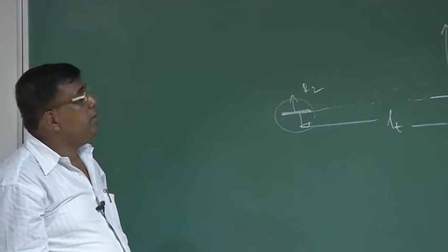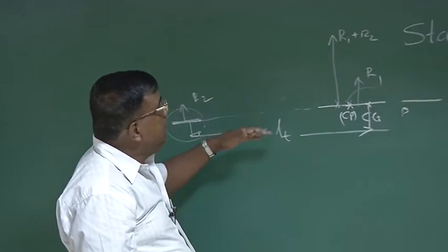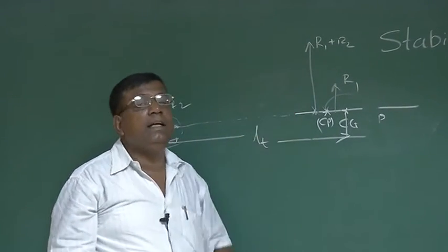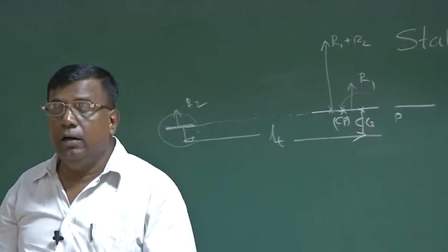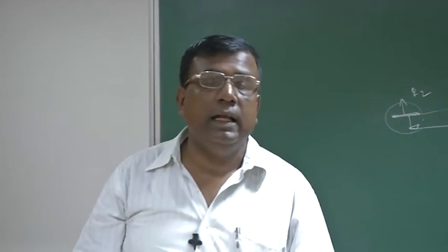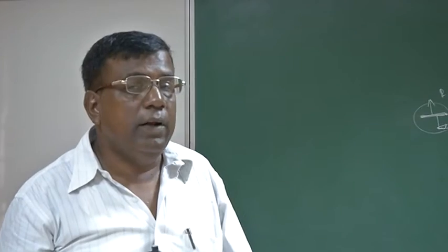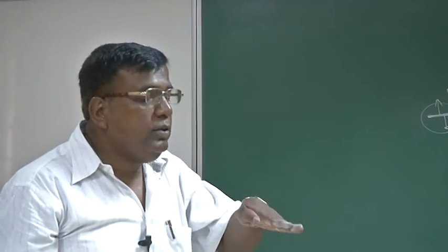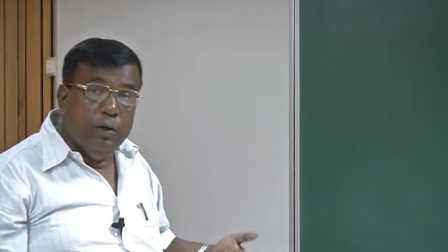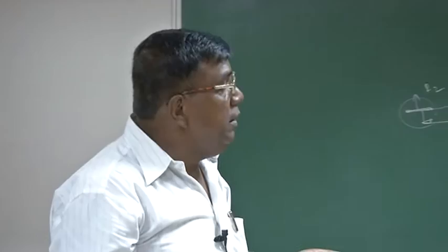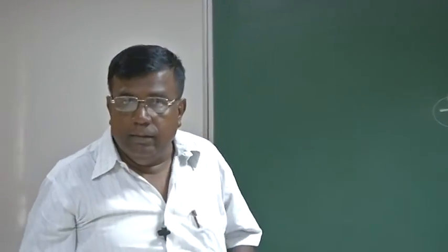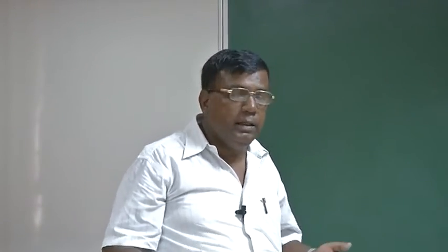But the next problem is severe, that I want to fly at different angles. I want to fly now at 2 degrees. At some other instant I can have a requirement to fly at 5 degrees. So I have to change the angle. So again I have to change from one equilibrium to another equilibrium. But since we have designed it statically stable, it will oppose, it will not allow by itself. That is the beauty of static stability.